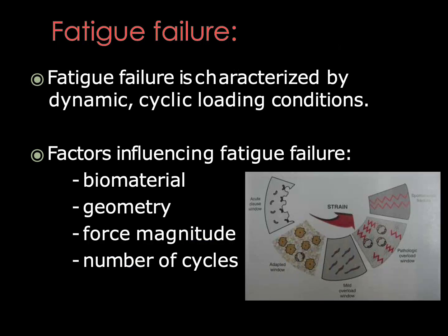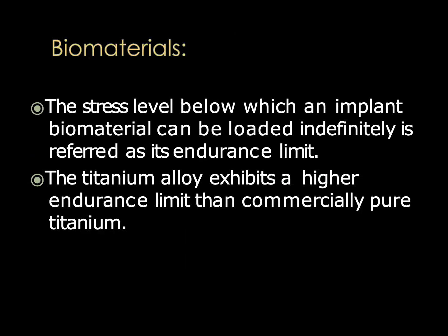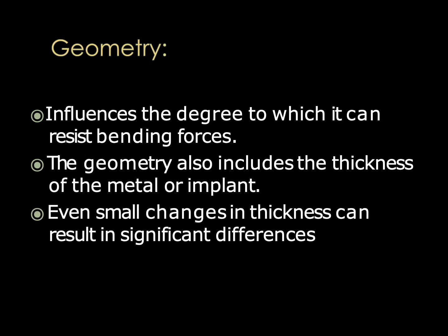Fatigue failure is characterized by dynamic cyclic loading conditions. Factors that influence fatigue failure are the biomaterial, the geometry of the implant, the magnitude of the force, and the number of cycles it is subjected to. Biomaterials: the stress level below which an implant biomaterial can be loaded indefinitely is referred to as the endurance limit. Titanium alloy exhibits a higher endurance limit than commercially pure titanium.